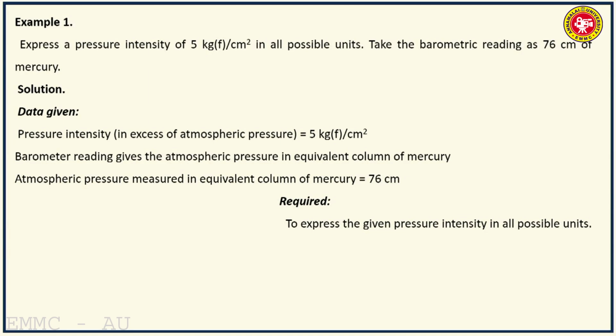So we stated Pascal's law, derived Pascal's law, or proved that the pressure intensity is the same in all directions, and we derived the relationship between atmospheric, absolute and gauge pressures. The gauge pressure can be positive or negative depending on whether the pressure at the point to be measured is above or below atmospheric. In expressing the pressure at a point we can use two datums, that is complete vacuum or absolute zero, or atmospheric pressure. When we are using atmospheric pressure as the datum, it is treated as zero even though it has a value. The atmospheric pressure varies with altitude and with temperature.